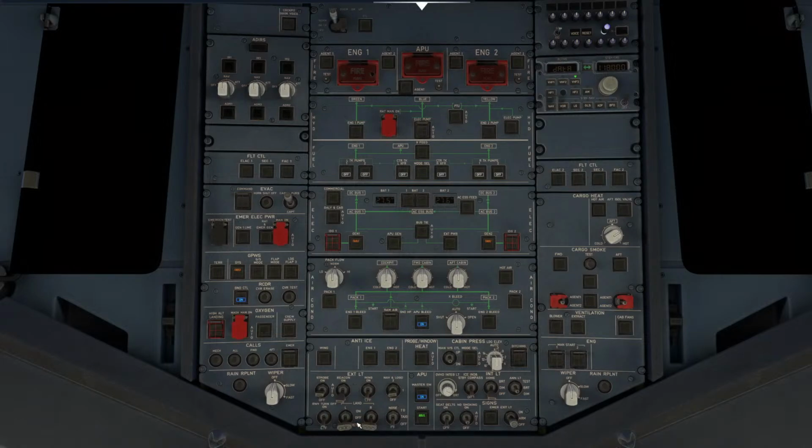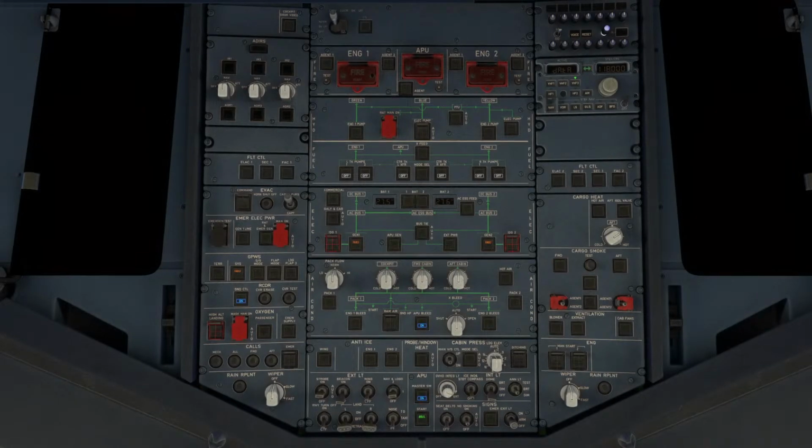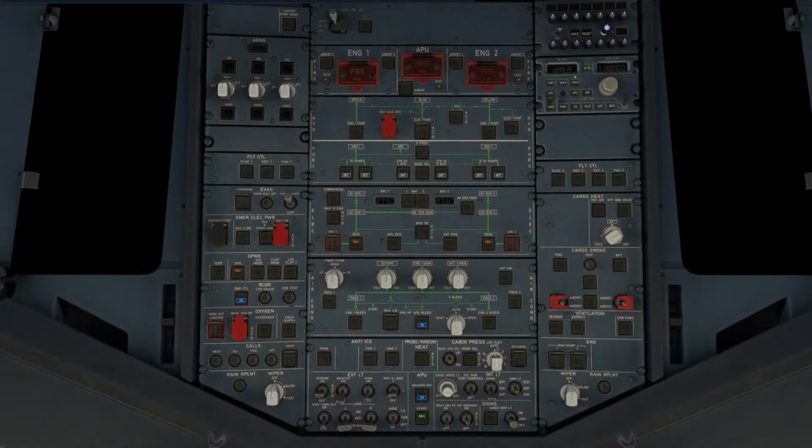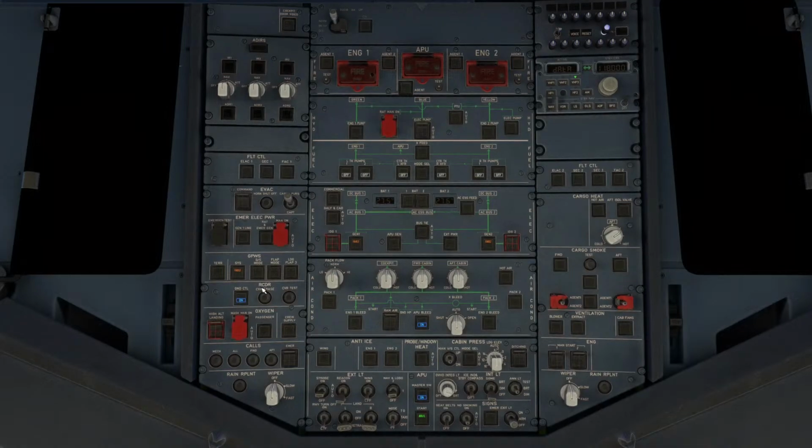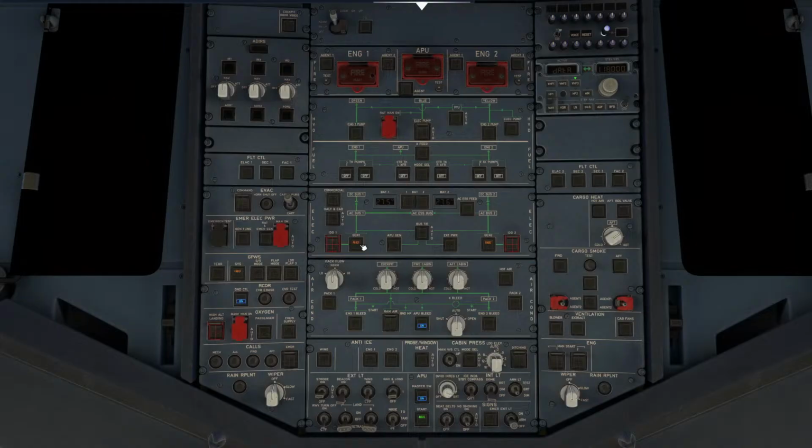You've got your exterior lights, you've got your fuel pumps. So this is the Airbus philosophy. Extinguish lights. If there are any lights that are not extinguished on the overhead panel, you gotta figure out what's going on. So, for example, ground proximity warning system is at fault right now. I'm not sure why. It probably has something to do with not having the engines on, the airplane's not moving, or something. The gens are faulted because the engines are not moving and the drive generators are not spinning. So the fuel pumps, you just get them on, and that'll extinguish them.